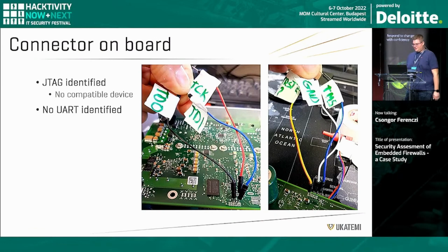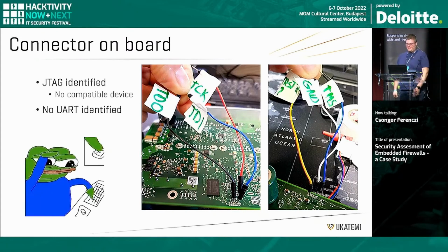While we managed to figure out the JTAG pinout, we unfortunately did not have a device which could communicate with this chipset, and we did not find a UART or other protocol on these pins, and since we had to keep the device operational, desoldering the flash chip was not an option, so we had to conclude the hardware side of the pen test at this point.